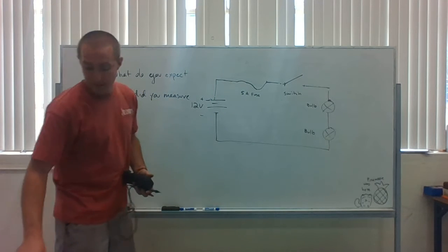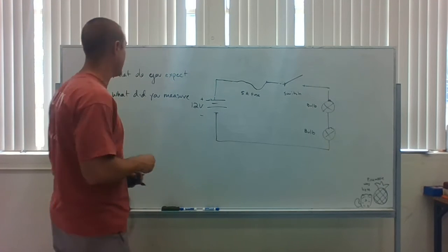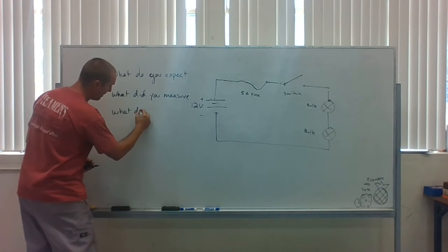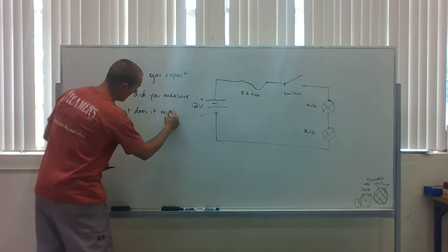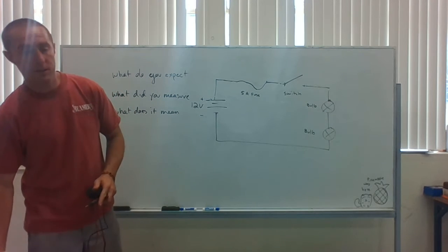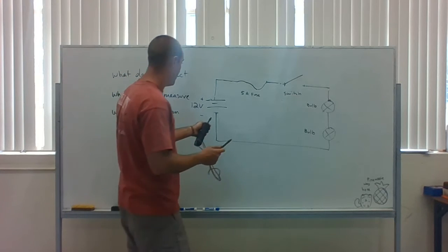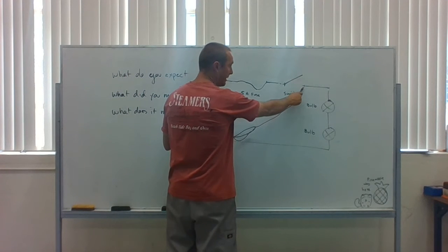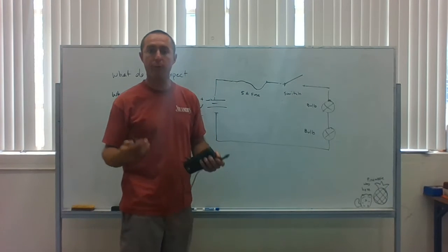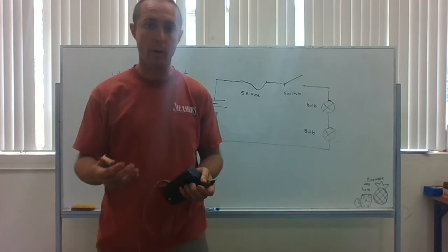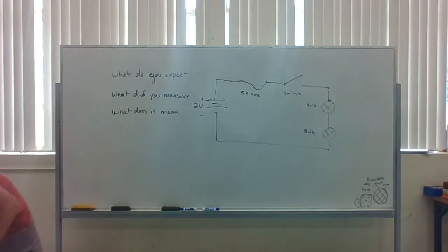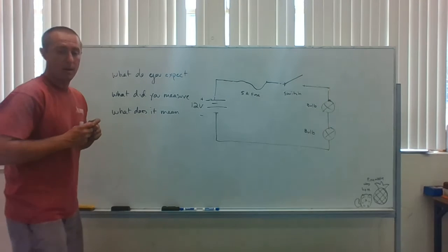And then last thing, what does it mean? Again, in this situation, if I have 12 volts right there, right now, with an open switch, that means that switch is probably bad. That's the first thing I'm going to look for, because that switch is probably faulty.